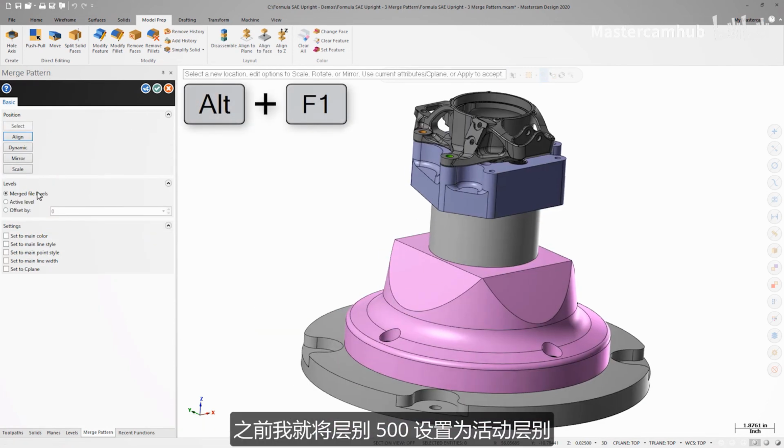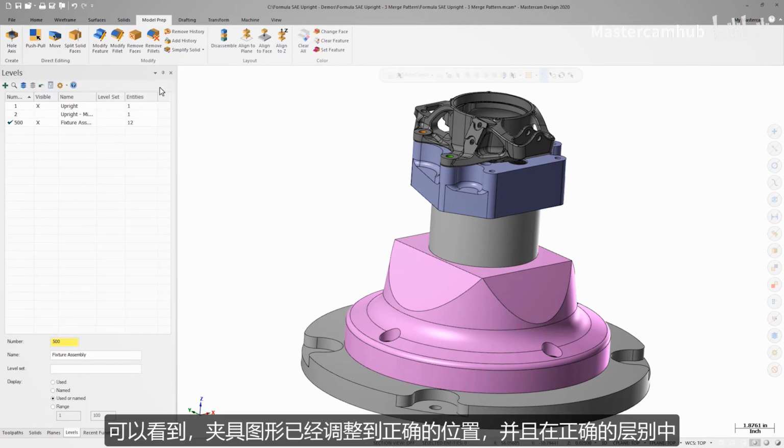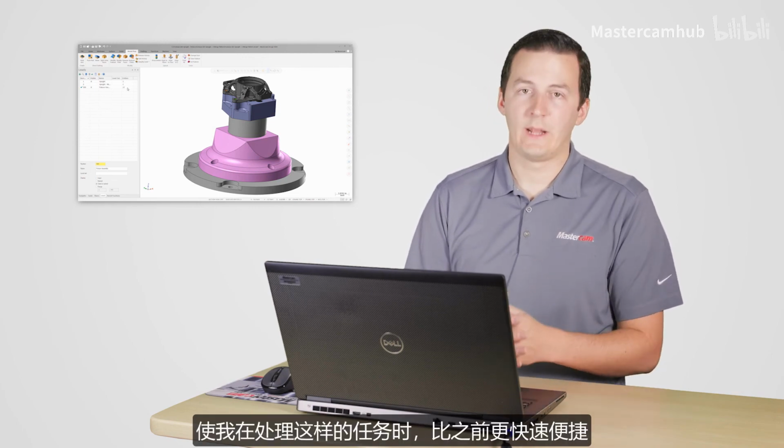I made level 500 my active level earlier, so I just need to make sure that my level option is set to active level. I can now close Merge Pattern and my fixture components are properly positioned and on the correct level. Thanks to the new features included in Merge Pattern for Mastercam 2020, this type of task is easier and faster than ever before.